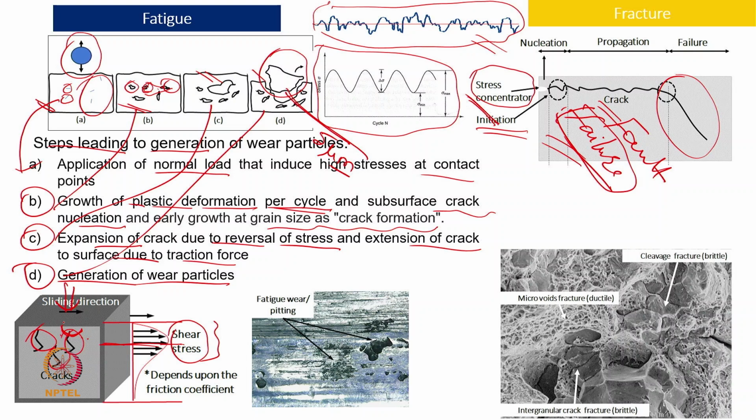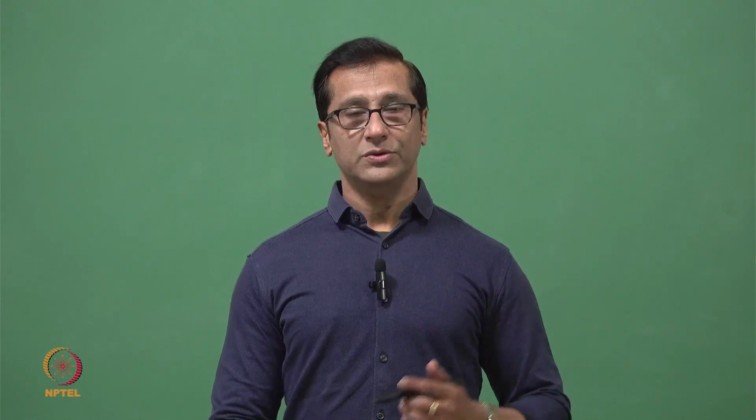Now coming to why these materials have inbuilt cracks: you can see ductile materials have voids, that itself can be treated as a crack. Even ceramic materials have granules, and they have cleavages also. So the grain bond itself can act as a crack initiator, or the nucleus of the crack, and that will be elongated based on that.